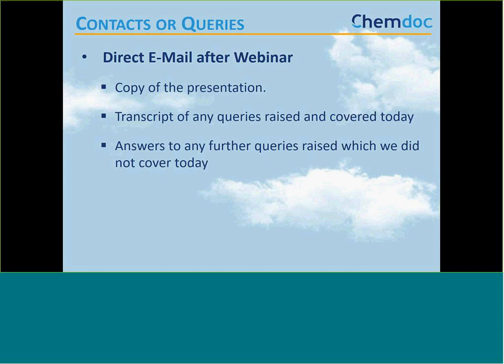And the point that she asked about briefly was just about signage of cabinets, in particular toxics. So yes, cabinets should definitely have signage or be marked with what hazards are in them. But I would take a step back from that first. Before you think about signage, you need to think about what products are stored in different cabinets, and in particular how they're segregated and how they're secured.